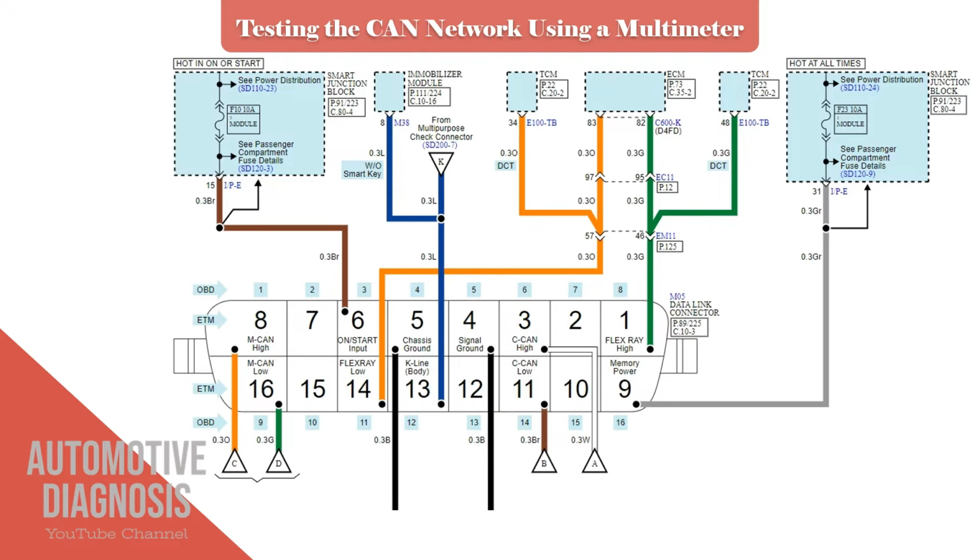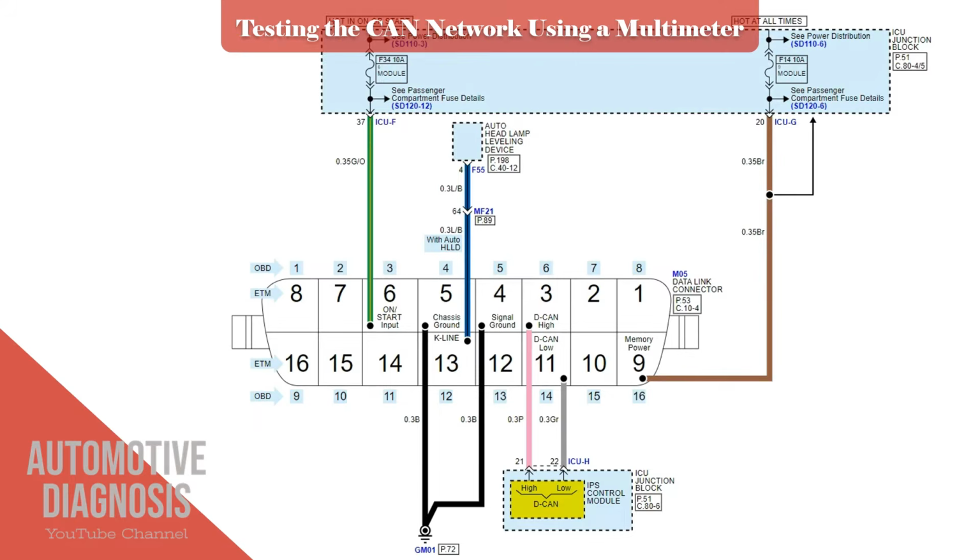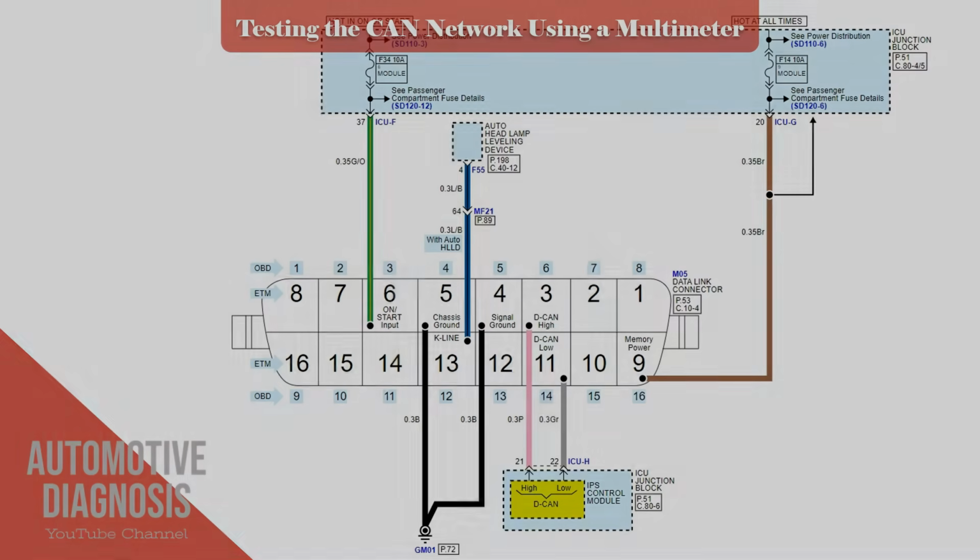But you must know that in some cars, there is a specific CAN bus for the scan tool, called DCAN or Diagnostic CAN, which may give you a different reading, as it is not connected directly to the powertrain CAN. So in this case, you must check the CAN bus from another place like the ECM wiring.